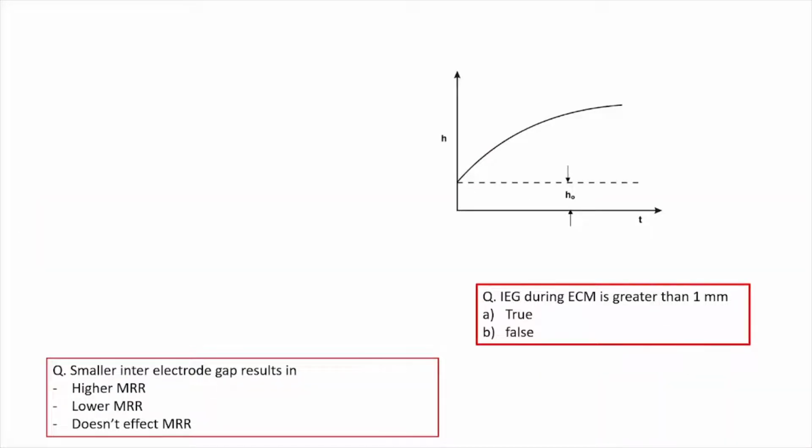And here, if we come to the dynamics of electrochemical machining, it can take place without any feed to the tool, or even by giving a feed to the tool it can be machined. Okay, so actually a steady machining gap is maintained in that machining process. So we need to understand the dynamics between the job and tool, in the electrolyte, and by giving a potential difference, how it works and what is the dynamics behind that machining process. Okay.